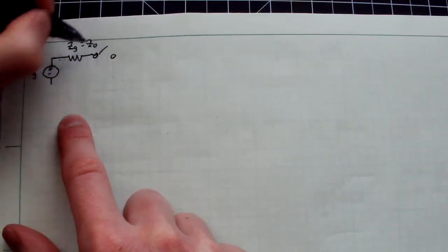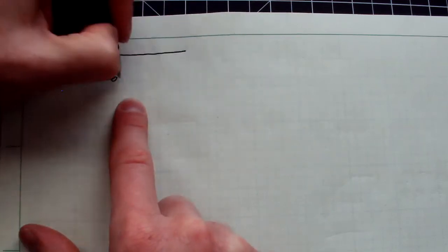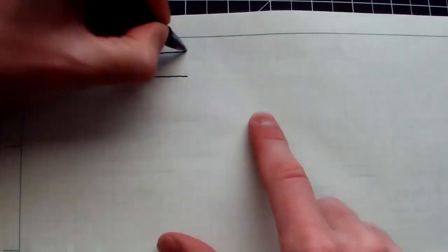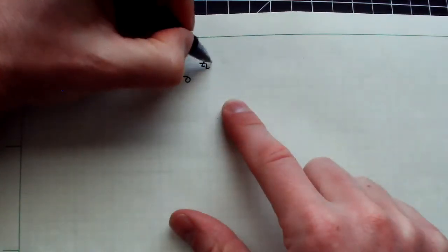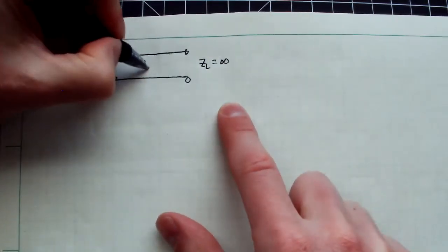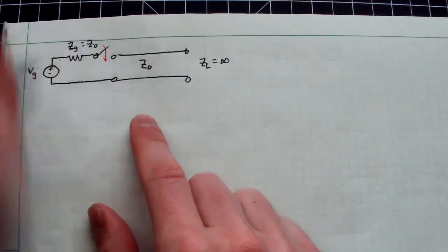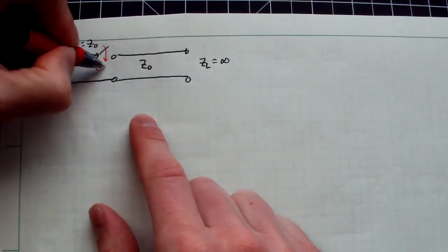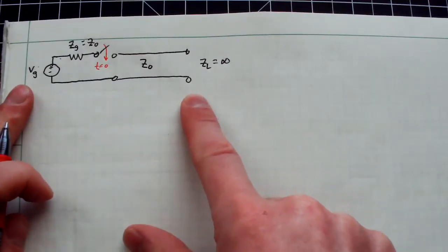And again, there's a little switch here, a length of transmission line, only I'm just going to leave it as an open circuit here. So you can essentially say Z_L equals infinity out here. And of course, there's the usual Z naught. So imagine in your head, what will physically happen when I close that circuit here? I close that switch at, again, time t equals 0, and now I want to plot the voltage along this entire line as a function of time.